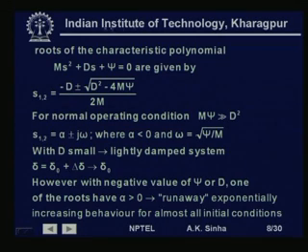However, if either psi or d, any one of them is negative, then the value of alpha becomes positive, and the meaning of this is that the oscillations will build up and the system will go into a runaway situation. That is, this machine delta angle will keep on increasing and it will be a runaway situation. This means that the generator will lose synchronism from the system.